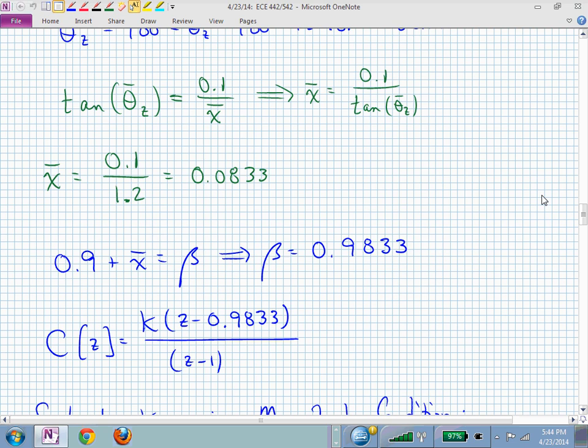And that's going to make for a pretty ugly overshoot behavior. Even though your triangles, if you just had a pure two-pole system, their overshoot is not too bad. Their zeta value looks pretty good if you can envision those logarithmic spirals that are inside the unit circle.